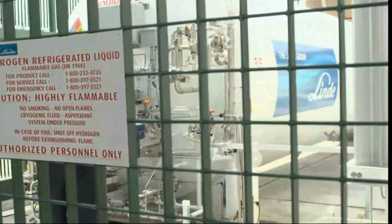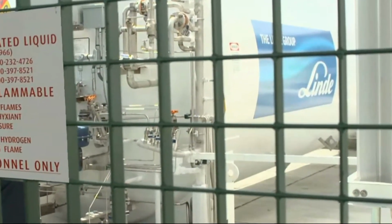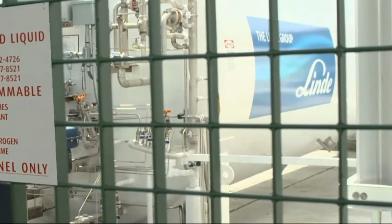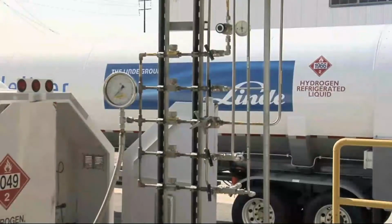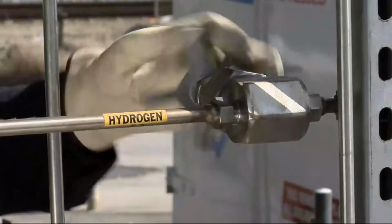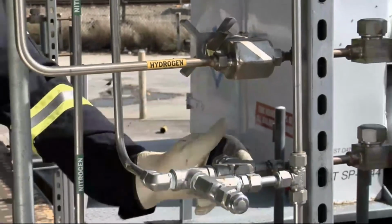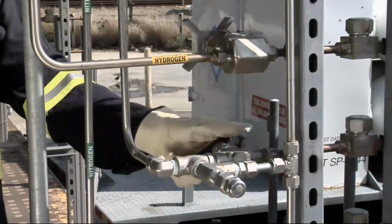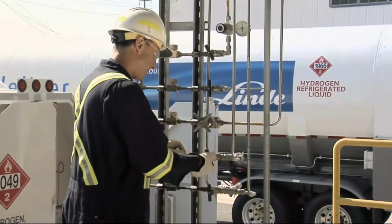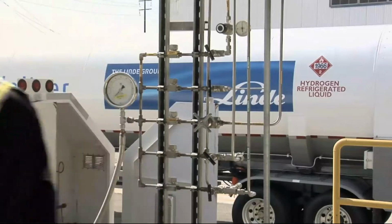Hydrogen bulk handling systems also need low-temperature shutdown devices. These prevent hydrogen that's too cold from entering any pipes or other equipment that are not acceptable for operation at very low temperatures. Sometimes liquid hydrogen systems must be purged to clear them for maintenance and inspection. Helium is the only gas that can be used for this process because it's the only one that won't freeze solid at the temperature of liquid hydrogen. For purging systems that carry hydrogen gas, nitrogen may be used, but product purity concerns may dictate that helium be used for this operation as well.